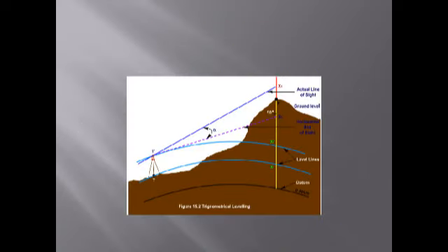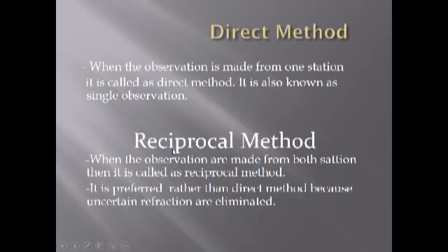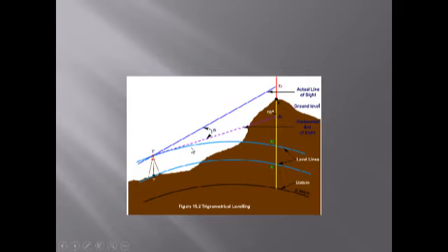This is the image we talked about on the previous slide. This is our tripod where we focus the object. This is object 1, x1, x2 height, and these are the leveling lines. This is the actual ground level. This is the tripod where we fix the theodolite. We focus the object x1, and this is the horizontal line where we measure the angle alpha.